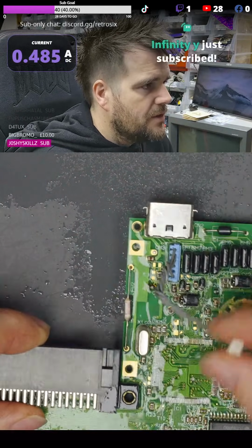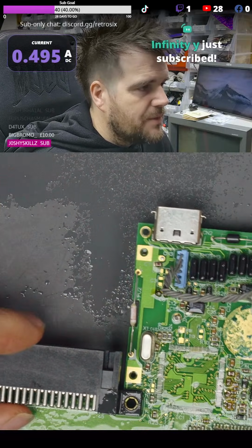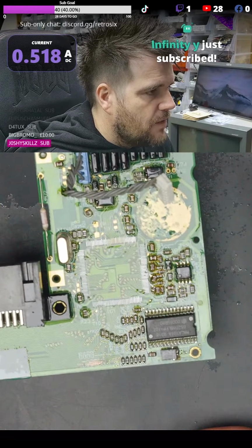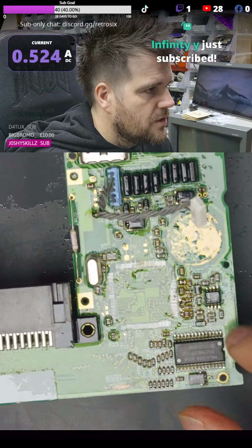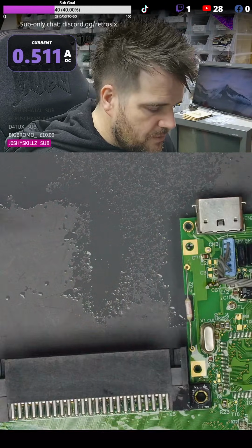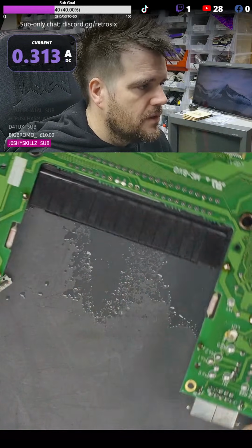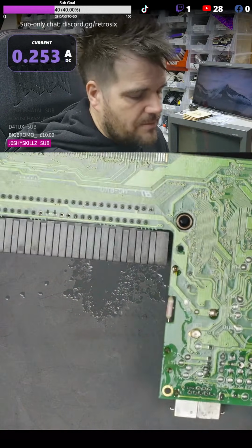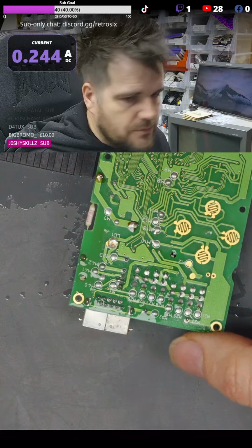But spraying IPA on, you can see even at 0.5 amp, you're not really going to get evaporation that obvious. It's going to be very hard to spot where a short is. Now, I'm going to show you where the short is, so we know, and then we can look at seeing if the methods work when you know directly where to look.